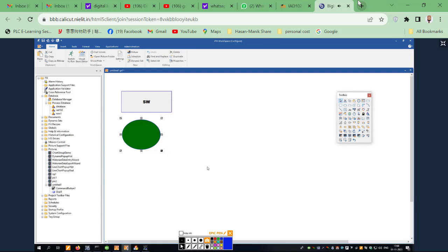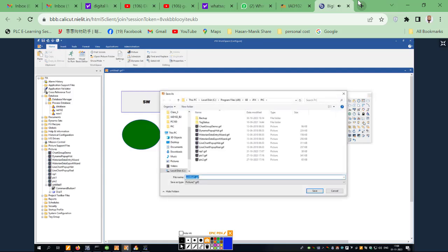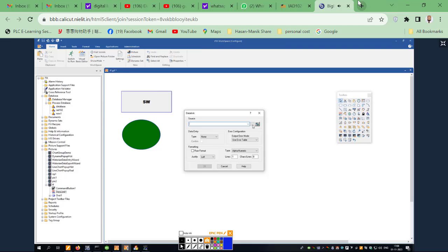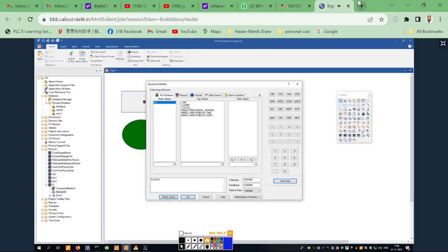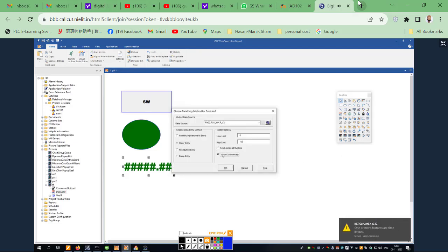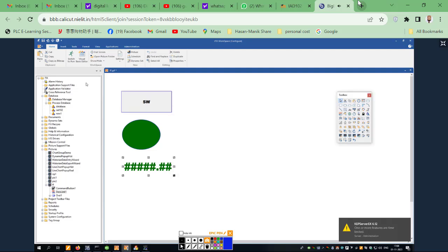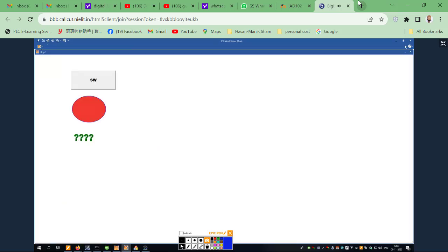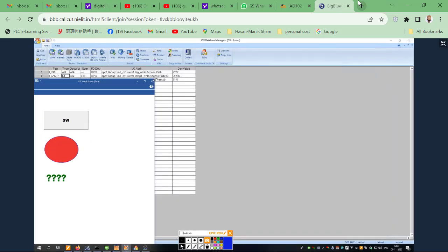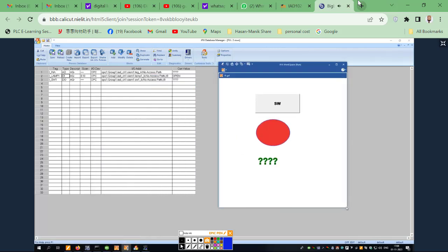This is the thing. Then if you want, we can send the value. Okay, send the value. That again you can go for the data link, slider, browse, iFix, input A, F underscore CV. All these things remain the same. Whatever we are doing in the simulator, same way we are doing. Then data entry expert, slider, write continuously. That's all. Save this one. Save. Now we have to run the picture. It will be running here. Here it is running. Okay.